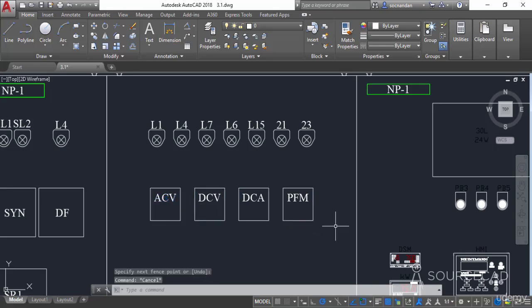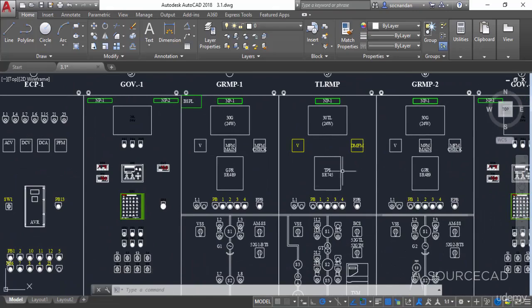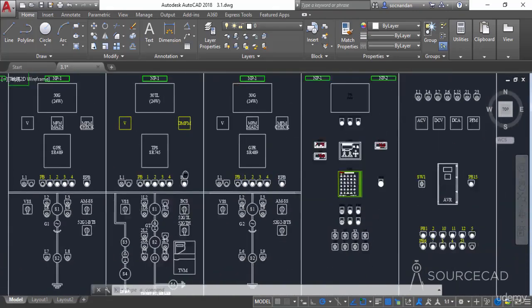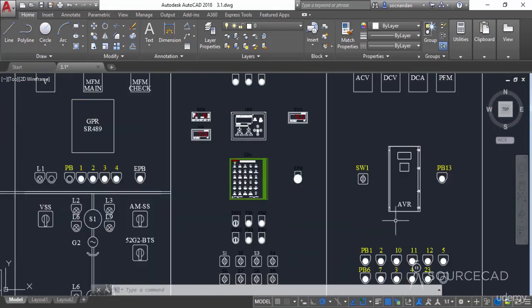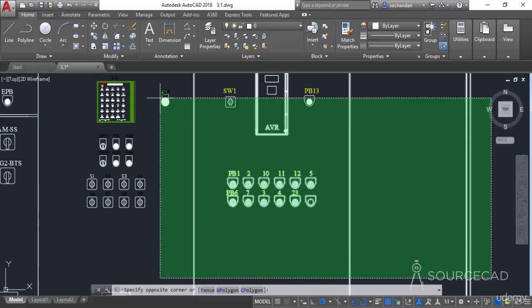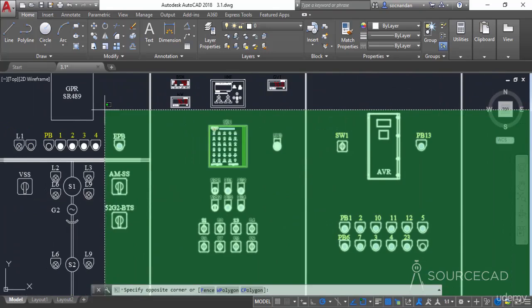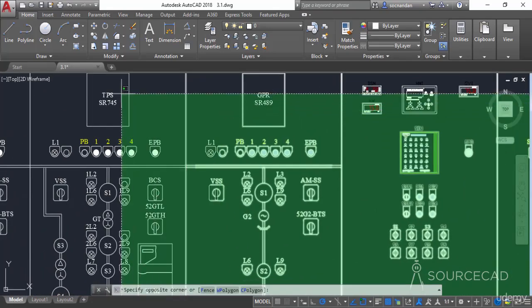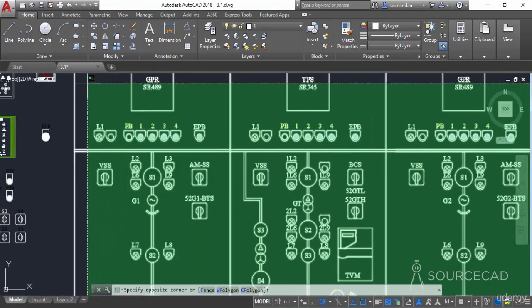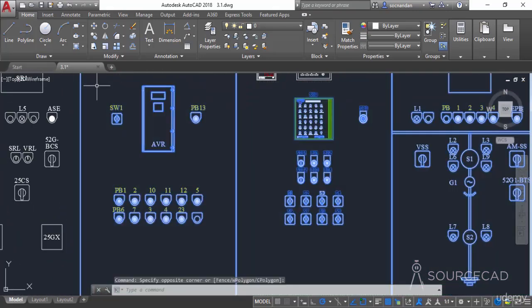In the AutoCAD 2018 version, AutoCAD added an off-screen selection, and the off-screen selection is helpful for selecting this kind of long geometries. So let's say that we want to make a selection by zooming this drawing, and we just want to include our selection somewhere from here. Now we are including the objects in our selection set, and along with inclusion of objects, we are also moving the drawing towards the right. So now we are scrolling it, we are panning it here, and now we are including many objects. Now let's click here.